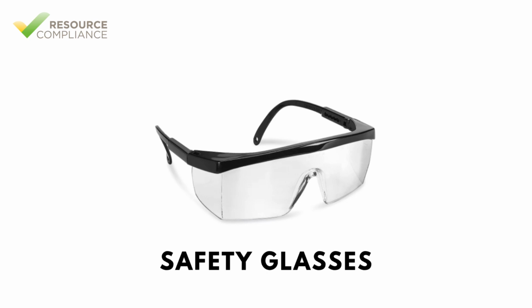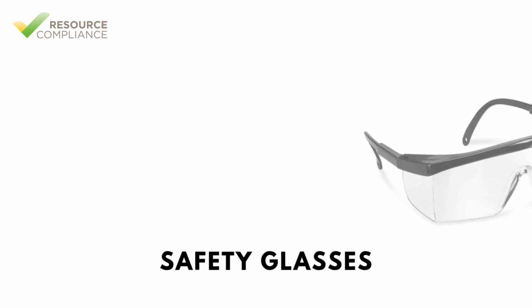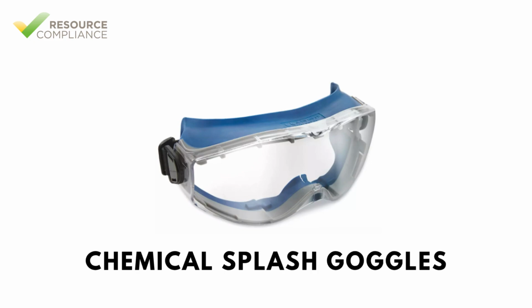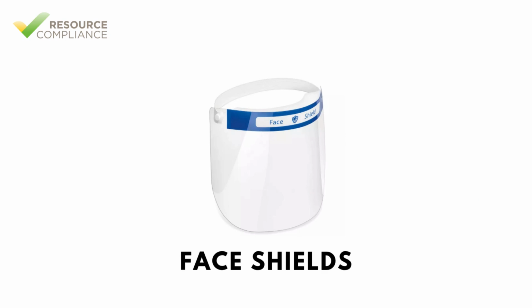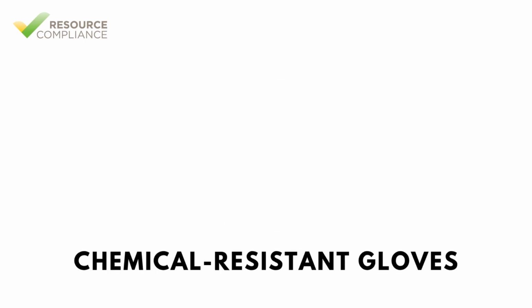Safety glasses are used for general protection against debris, dust, and light chemical splashes. Chemical splash goggles are required when handling refrigerants, condenser chemicals, or other hazardous liquids. Face shields are used in combination with goggles during line breaks, charging operations, or where there's a risk of liquid refrigerant spray or arc flash.